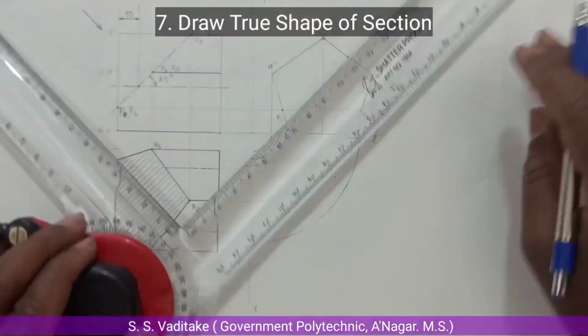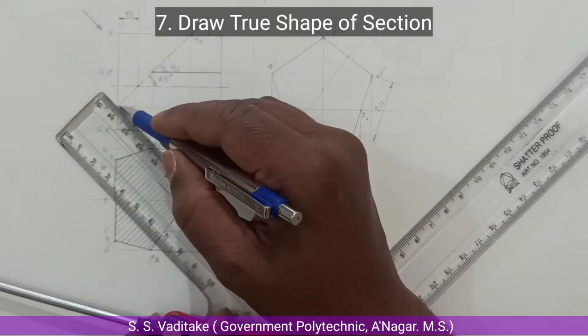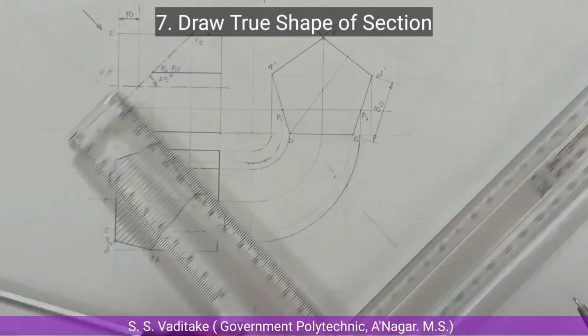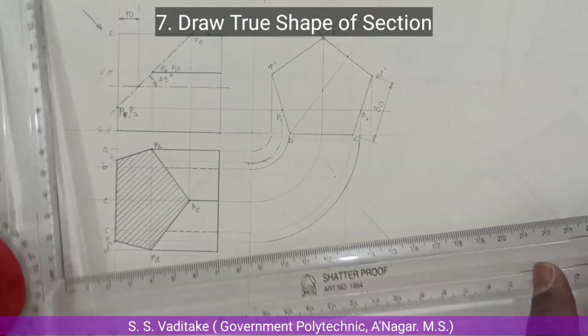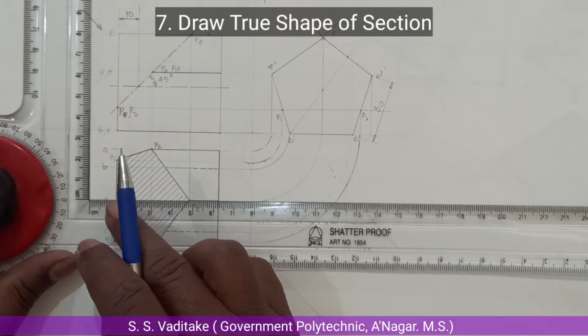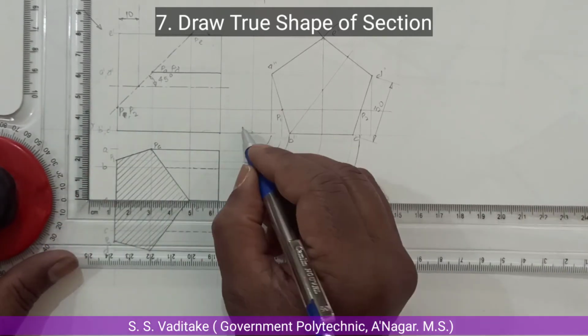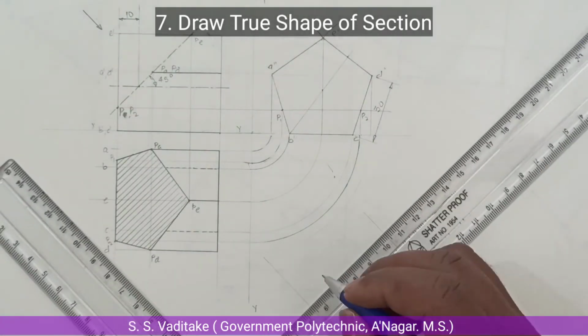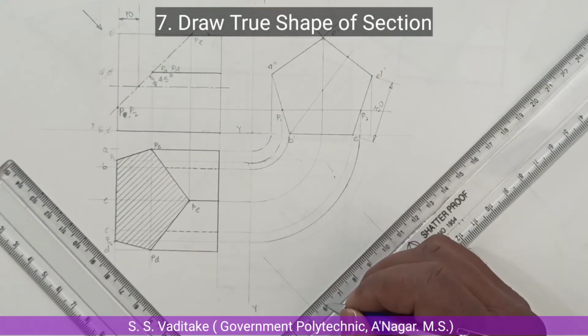Now to show the true shape, we are observing at a right angle to the section plane. So draw the projection lines through the cutting points which we have marked in the front view. If you observe, the sectional top view is symmetrical about the edge E, so take this benefit.